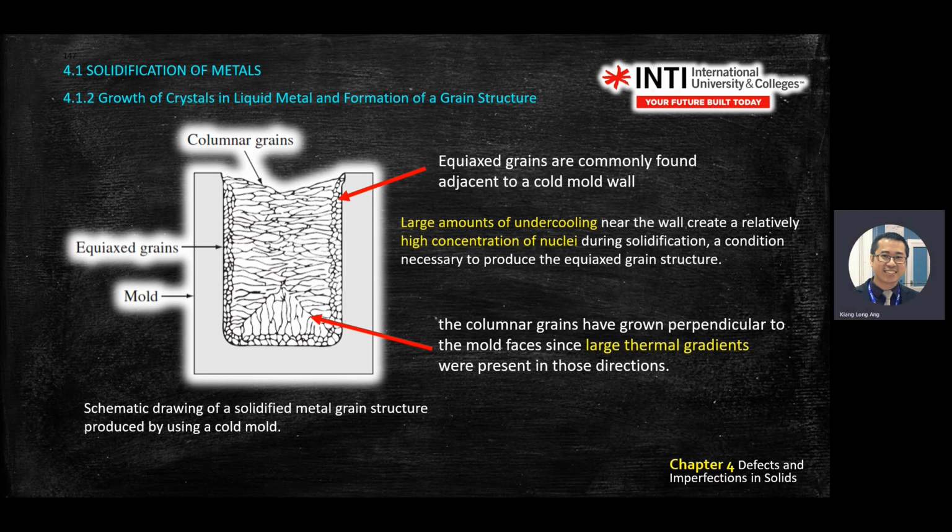If you have this kind of mold shape, the columnar grain grows perpendicular to the mold face. The direction is perpendicular, right? 90 degrees to the surface.